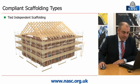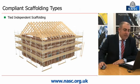Independent tied scaffolding. It features unclad, brick guarded, debris netted or solid sheeted. Bay sizes up to 2.4 metres. Note there is no 2.7 metre bay size included. We see the welcome return of single bay facade bracing without the need for additional plan bracing.